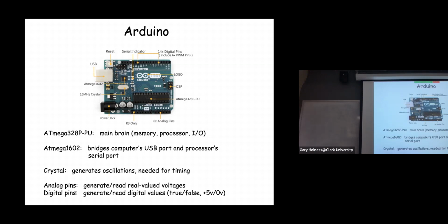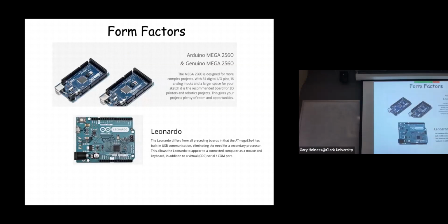But what do you do if you have an application that requires a lot of input output? For example, what if you have a robot mechanism? If your robot mechanism is what's called a 7 degree of freedom arm, a degree of freedom in robotics, you can think of it as a rotational axis driven by a motor. And so if my arm were robotic, I'd have one motor to make it do this. I'd have another motor to make it do this, another motor to make it rotate that way. So that's 3 motors.